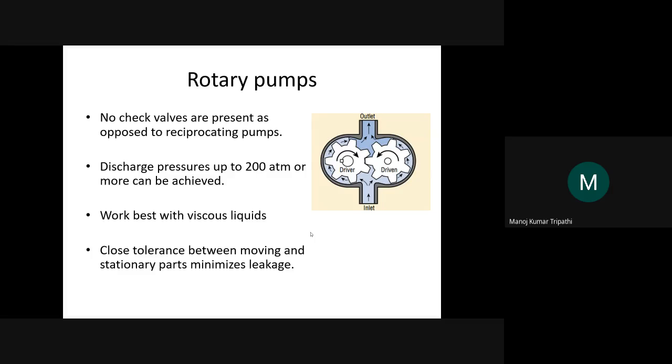Now these kinds of pumps, another category is rotary pump. So this is different from a centrifugal pump. There's a different term here, rotary, which means that the fluid rotates with them and it goes to the outlet. Basically, it is not because of centrifugal action that the fluid is moving. It is just rotating in this cavity and moving.